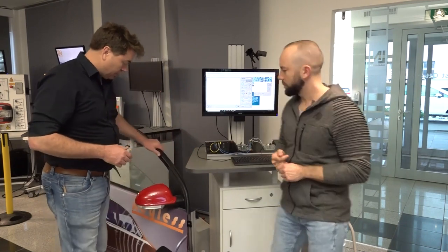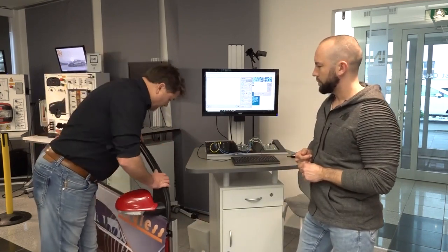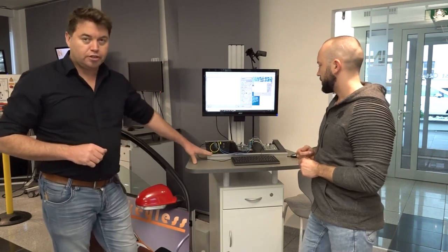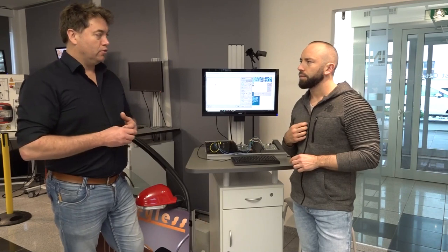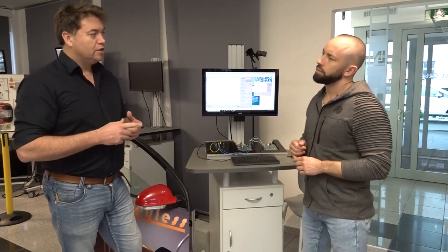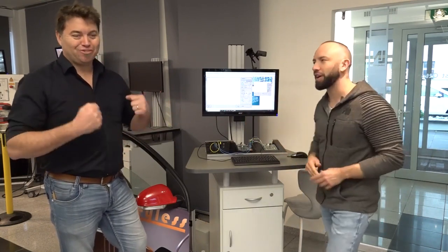Yeah, exactly. It's a good point. If you have a look on a real vehicle, you've probably heard about CAN bus, and that's where you've got the twisted wires. They call it the twisted pair. You'll often see them in the vehicle, but obviously these are all hidden away, under the door panels and things like that. We actually have a door connected here with our Unitrain system, and we're going to have a look at what it looks like on this today, because it's easier to access and to see what's going on behind the scenes. As far as using a real vehicle, there's only really one place that's easy to access without removing door panels and things like that, or drilling a hole inside the chassis of the car.